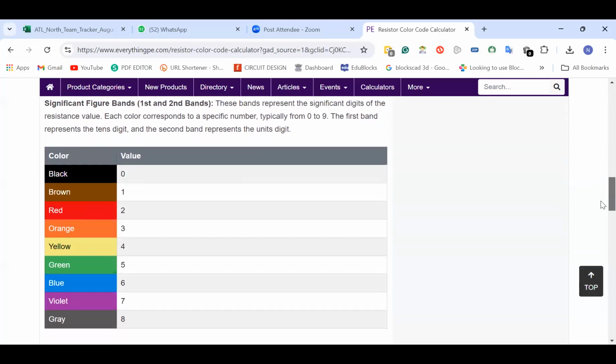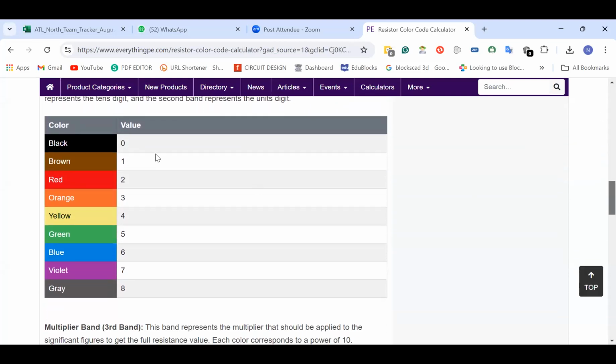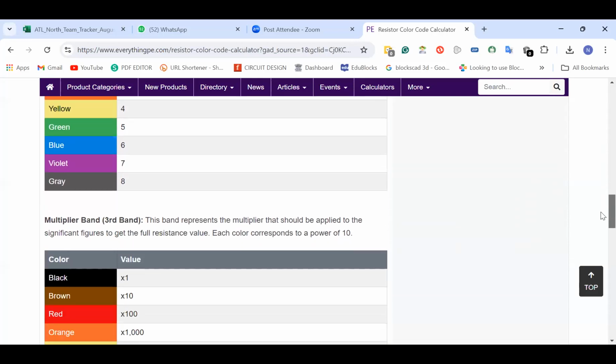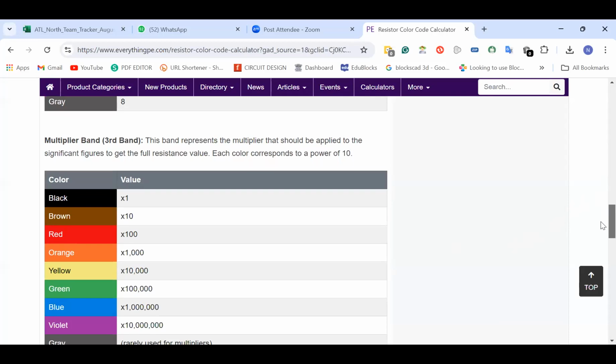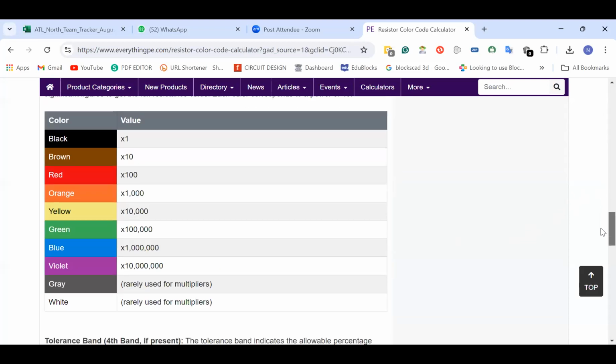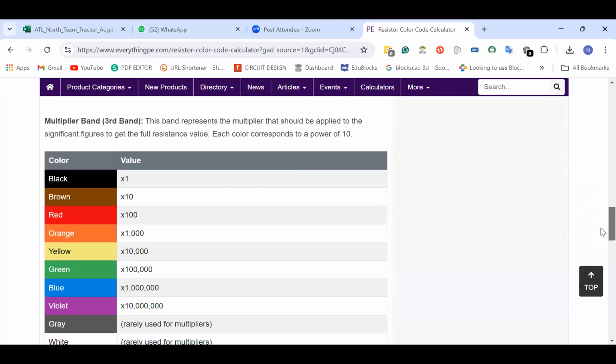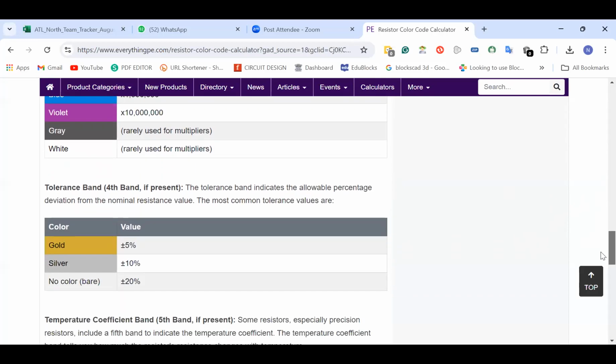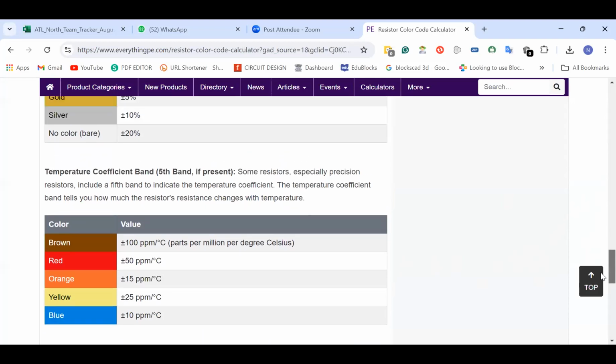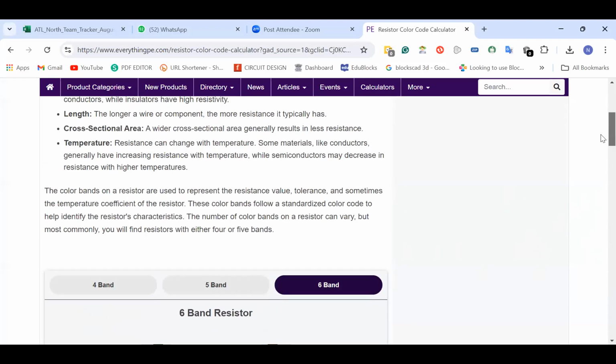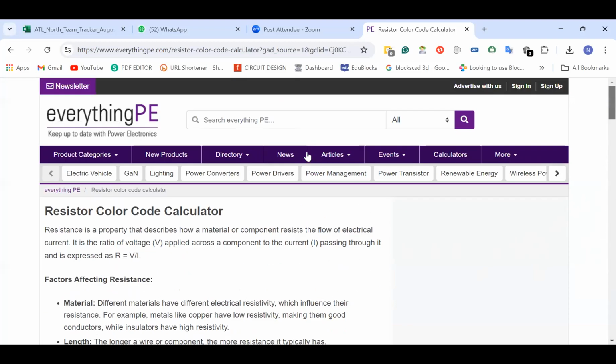So similarly, this is the color band we are talking about, the gray one. It's fine. So this is how you can calculate the values. Then this is the second, this is the third, and this is the multiplier. To multiply, it basically denotes how much power it can tolerate, right? And this is the tolerance value. Fine. So I hope this one is now clear to all, of how to calculate the values of the resistance.